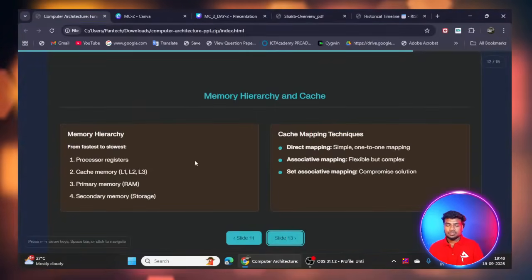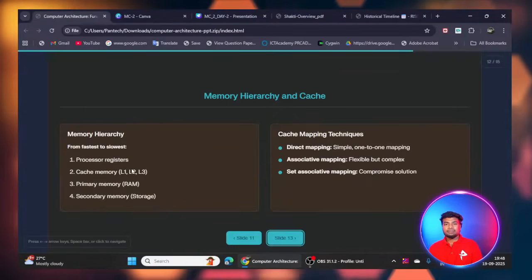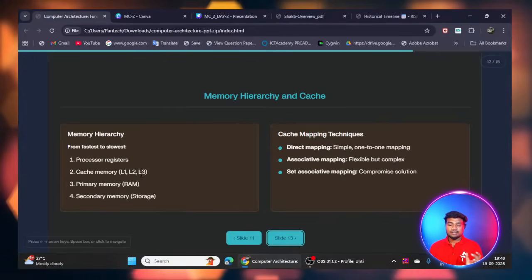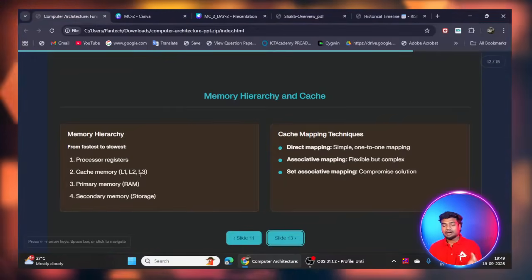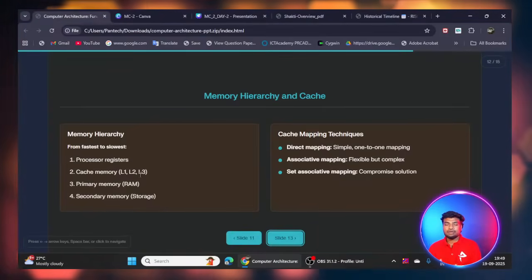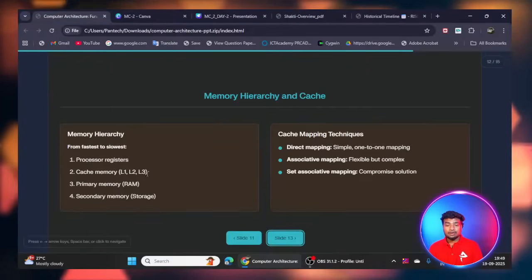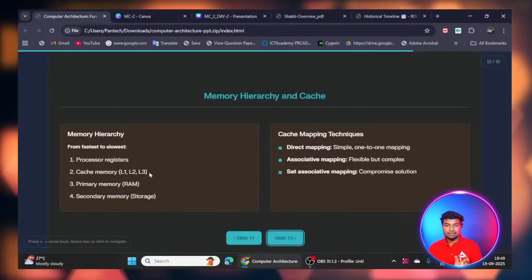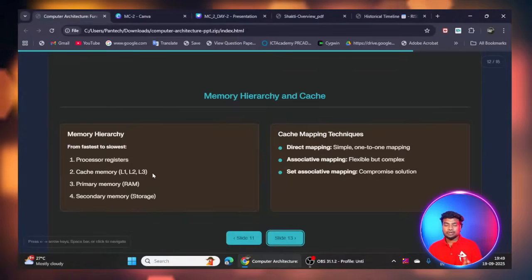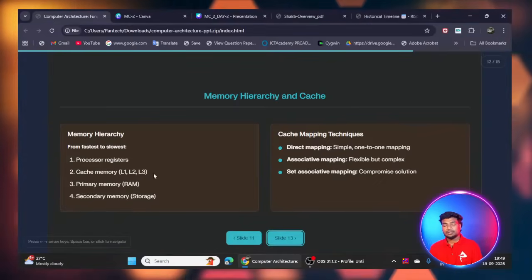Each and every processor core has L1 cache, L2 cache, and L3 cache. L1 is very small in size, but very near to the CPU. L2 cache is much larger than L1 and a little far from the CPU. L3 cache is larger than L2 and farther from the CPU. When I get into SoC, I will explain what L1, L2, and L3 are.